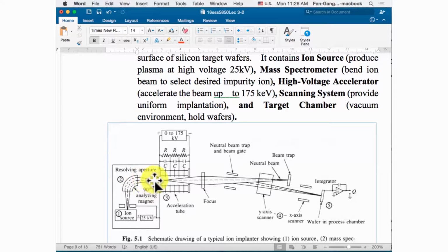After they come out, we select the ions we want, and then we accelerate the ions using the accelerator, which uses an electric field to speed them up. So the ions become the shots in the shotgun, shooting out from the shotgun. We can shoot those ions onto the final target, our wafer.